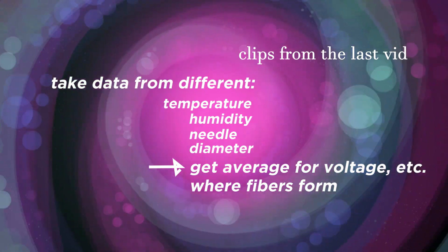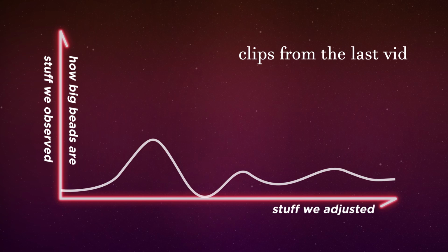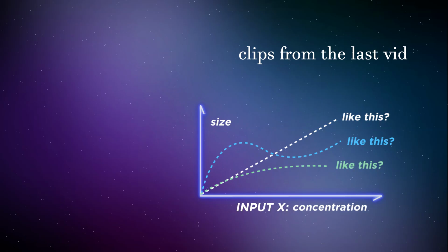Anyways, so in my last video, I talked about how I wanted to use machine learning for my internship with a biodegradable plastic. I set up the general aspects of how ML works, and that's all about relating properties we have control over and properties we want to maximize or minimize. So my specific example was with beads. We don't really want beads, we want to make fibers, we want long fibers. And there are specific voltage values or tip to collector distance values that make it more likely to get those defects, those beads. So we want to try to stay away from that.